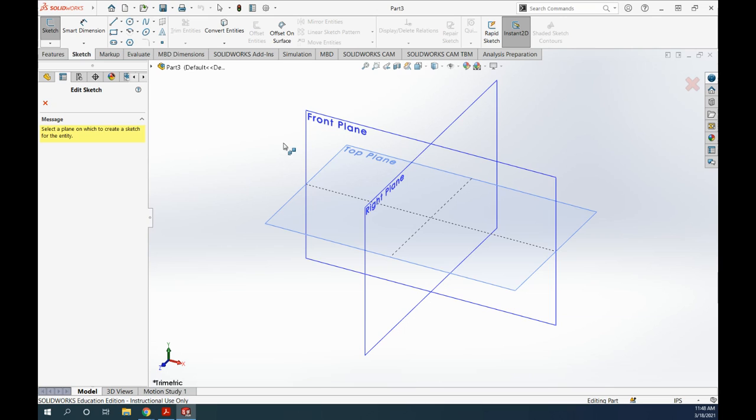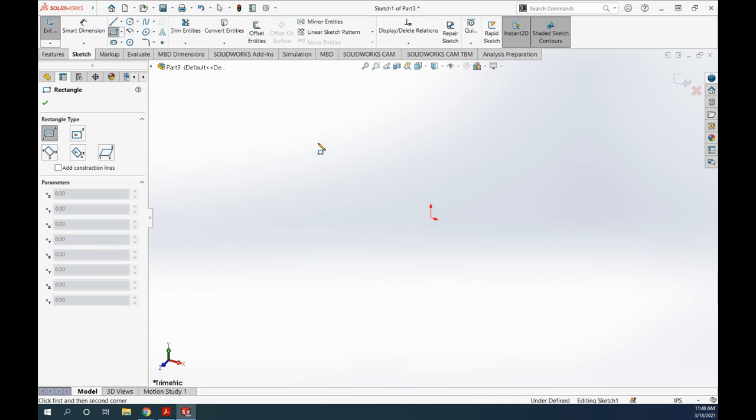So you notice there's a whole bunch of stuff we could have selected, but we're going to start with a rectangle shape. Now, when you click your basic sketch type, you're going to get this screen, and that is going to show three perspectives, and these are related to technical drawing techniques, and it does kind of matter which perspective you choose. A lot of the time, we're going to be going from the front plane or perspective. You see we also have top and right, but for today's, we're going to be going with the front, so I'm just going to click that.